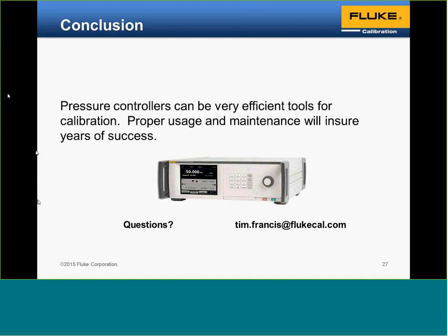This question is, does the Fluke COMPASS for Pressure allow for calibration of a device under test using an averaging feature because of differing readings? Yes. You can decide to average over a period of time or average a number of readings from the device under test, in situations where you have different read rates on your controller or your device under test.